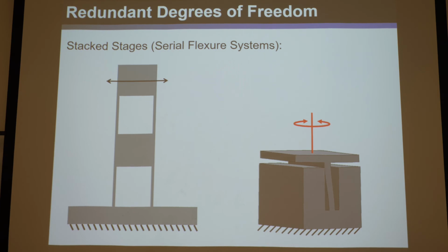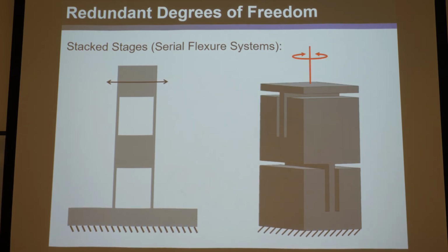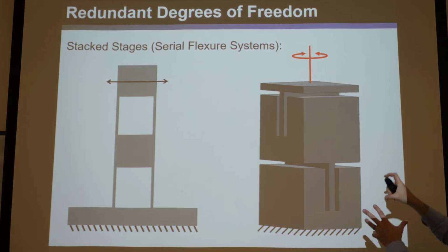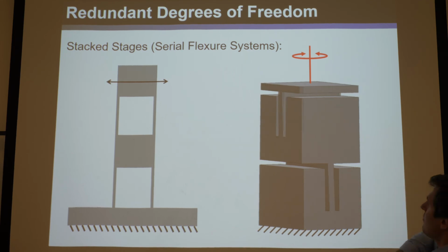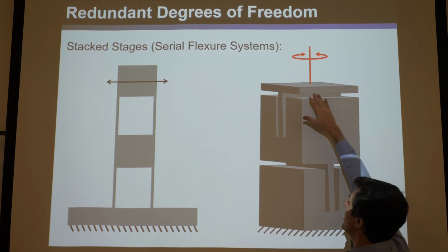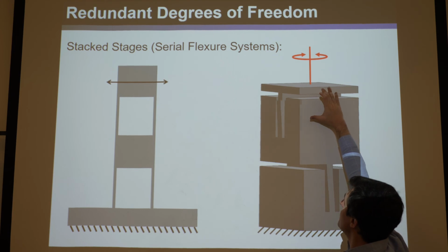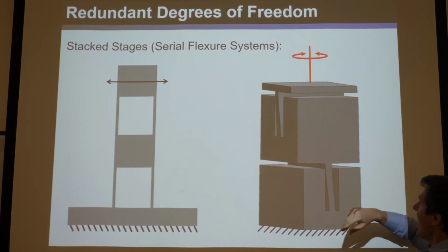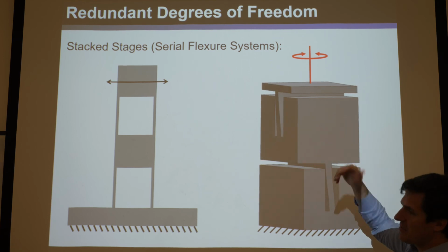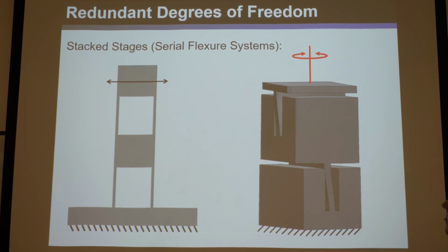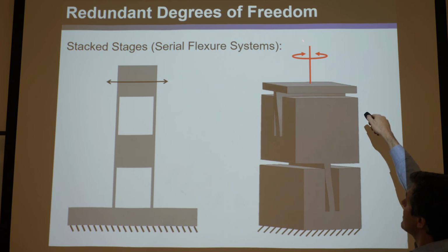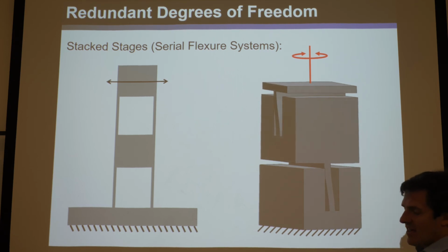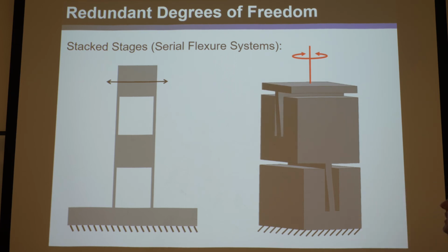All right, but now say I stack this guy in series with itself. So now we've got two parallel modules stacked in series. We've got three rigid bodies. One is ground. We've got two bodies that can move. Here's this one. Here's the stage that you care about. Okay? And I stacked them. Notice I turned it 90 degrees, whatever. Right? They both independently achieve this same rotation. And that rotation is in the same location, in the same direction. So it's the same degree of freedom.